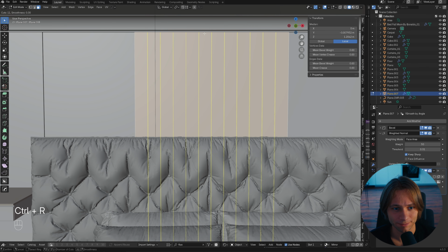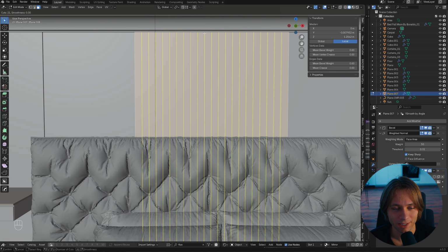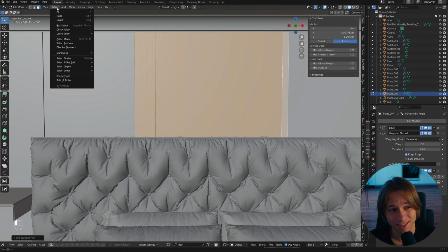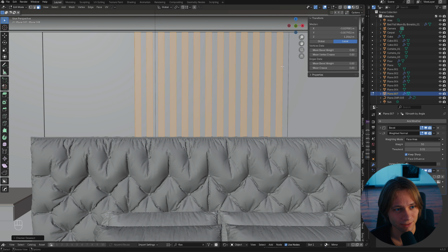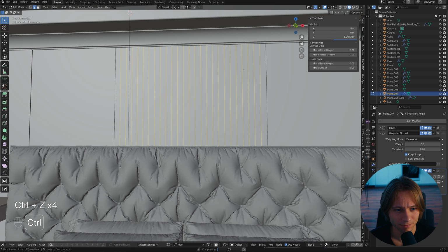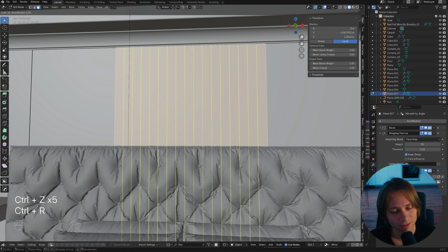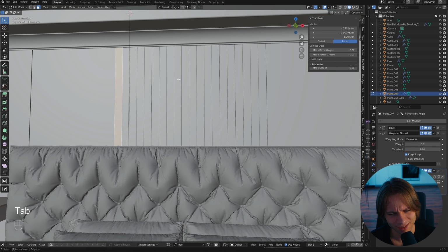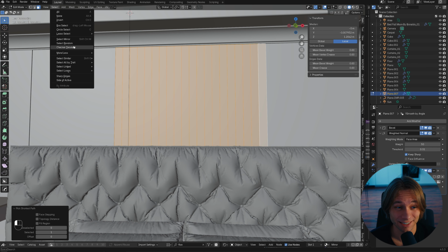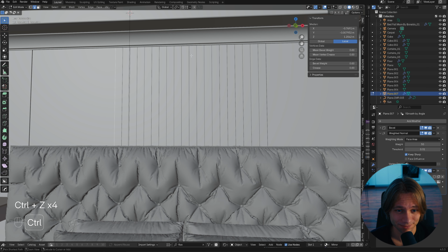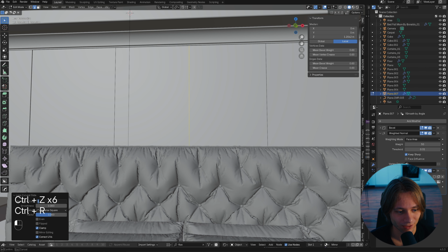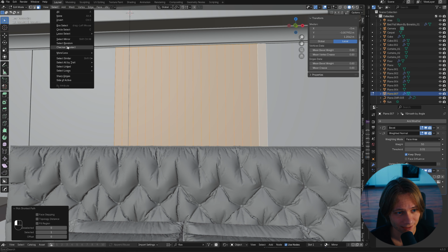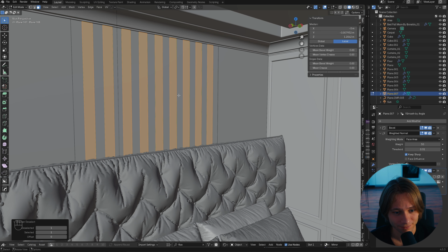Add some loop cuts to the middle panel to make some extra panels for extra detail. Select all edges and press select checker deselect. We had the wrong number of loop cuts. This one will be wrong too. You need 18 to make it symmetrical. Now let's add 18 loop cuts. Select them, faces, check the select, and extrude this.